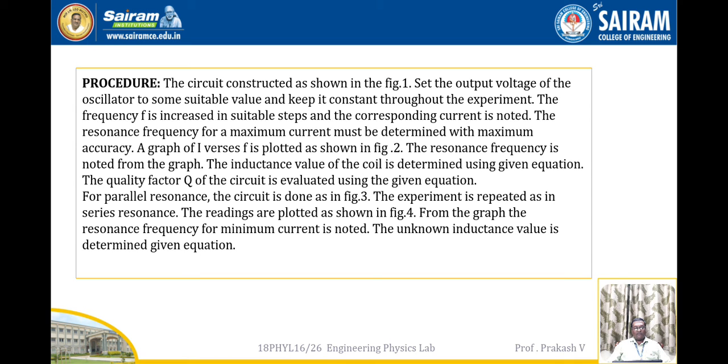A graph of I versus f is plotted as shown in the figure. The resonance frequency is noted from the graph. The inductance value of the coil is determined using the given equation. The quality factor Q of the circuit is evaluated using the given equations.